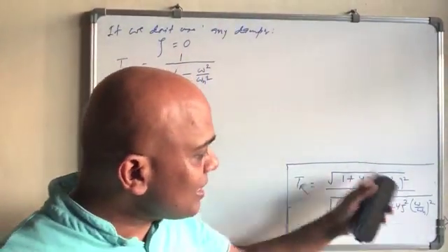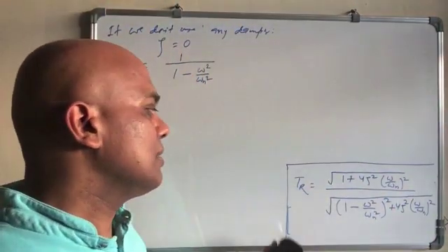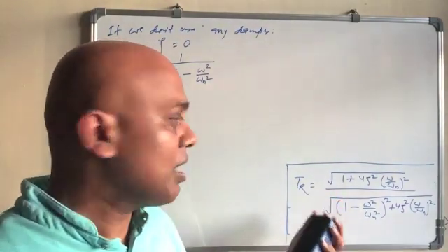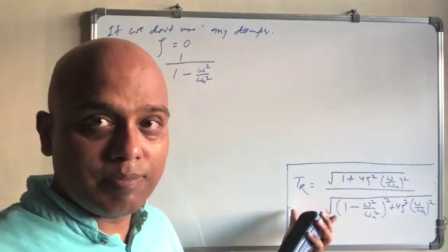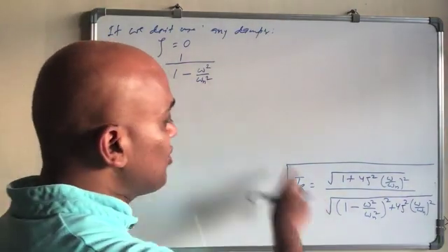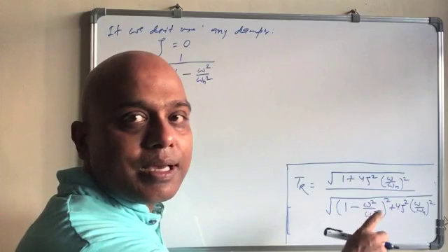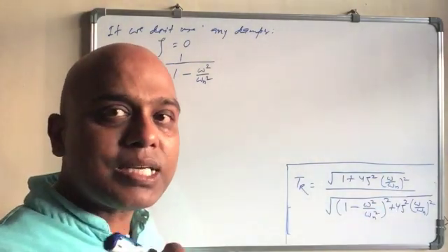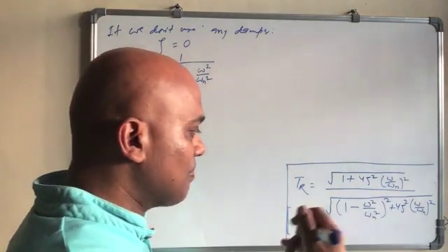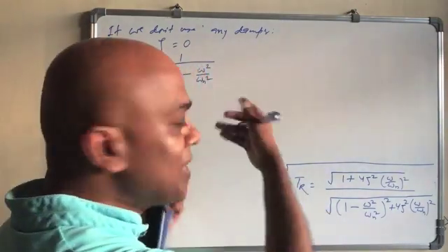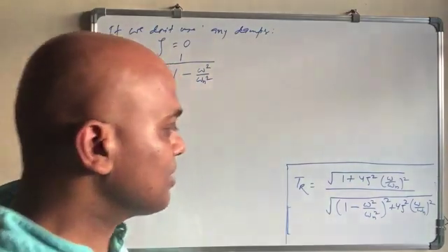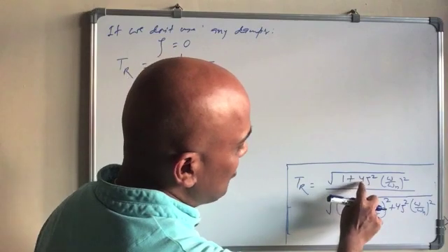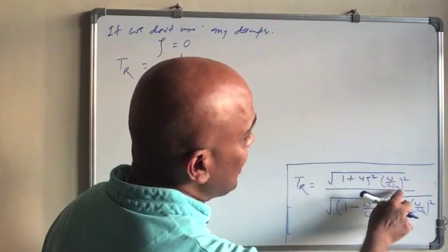Now looking at this equation, you can also see what will be the desirable parameters for a good engine mount, right? So one thing is not to match the frequency of the excitation force with the omega n of the system. That will be one thing. Second thing, see here, it is 4 zeta square (omega over omega n) square.